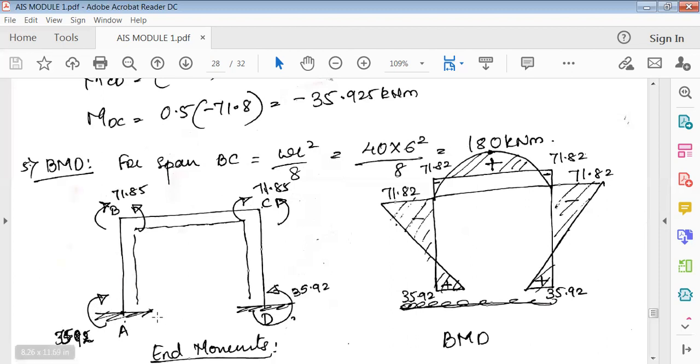Because it is trying to push it inside, obviously this frame moves inward. This part moves to the right side. So I've shown here, this is the main original column. Because this moment is trying to push it here, it goes to the right side like this. Next, we'll take this part of the beam. If it bends to the right, to keep the beam in equilibrium, at this part it should bend to the left. Only then would the right side and left side bending be consistent.